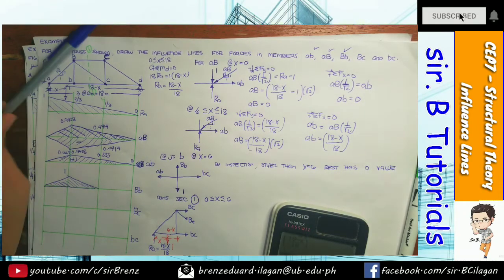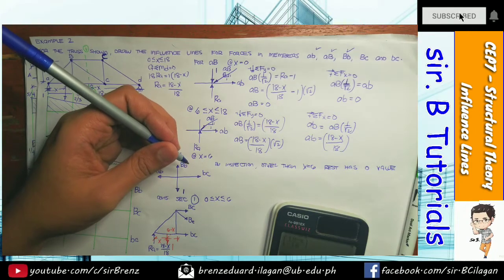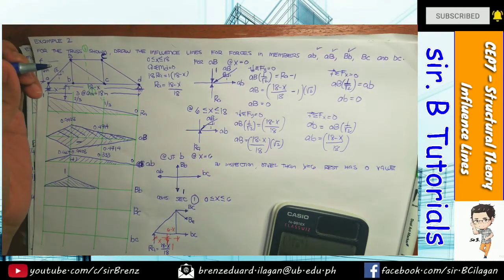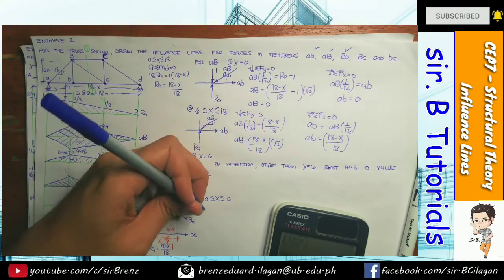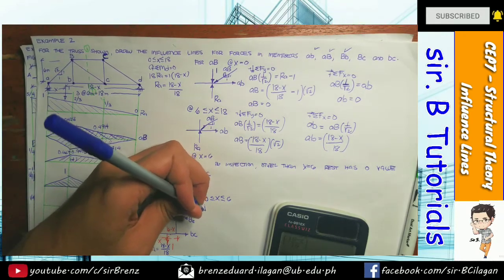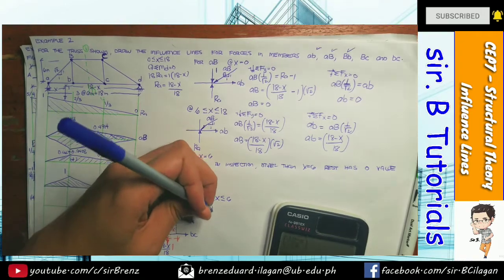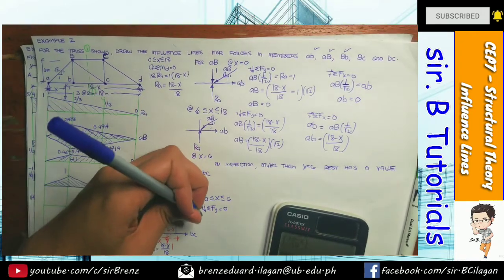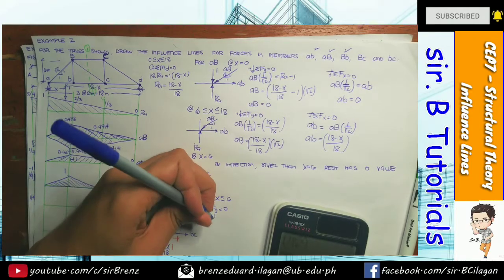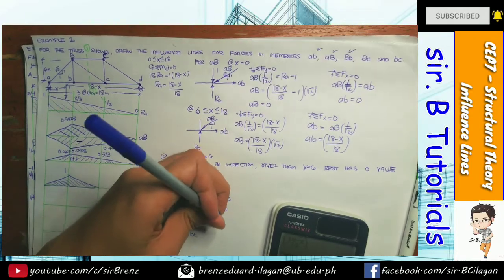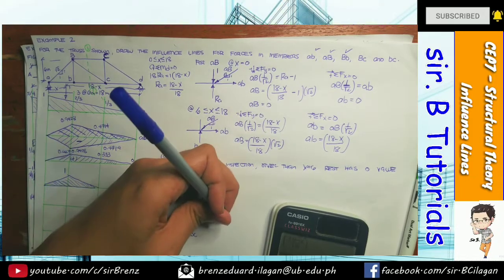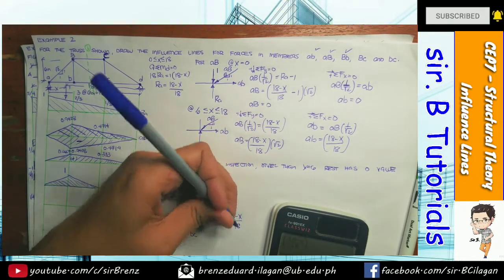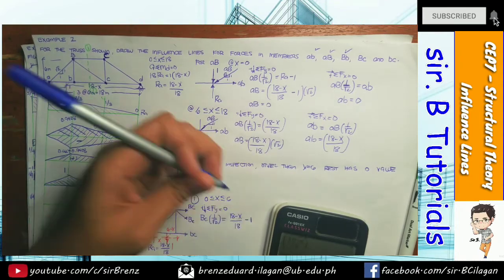Okay, so ganun lang ulit. Ano bang gusto nyong gawin? I think mag-summation tayo ng forces ng Y, okay? Assuming downward direction is positive, take summation of forces ng Y equals to 0. So the equation will be BC multiplied by 1 over square root of 2 is equals to RA, the 18 minus X all over 18, and then minus 1.